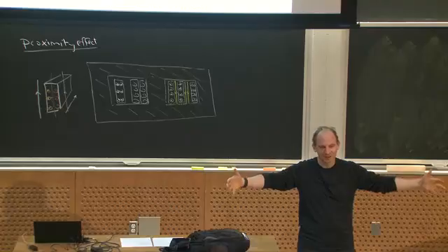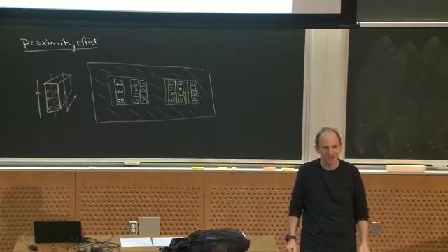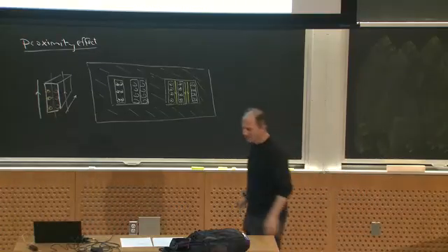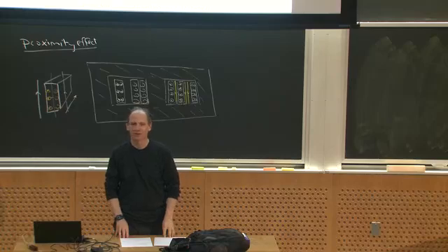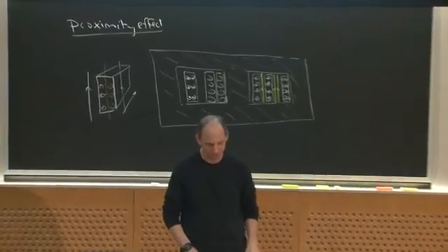If I'm building a 60 hertz transformer that's carrying an amp, my conductors are naturally going to be much less than the skin depth, and I wouldn't even think about it. Okay, so that's winding loss, right? And these are just some things to think about. Watch out for skin effect and really watch out for proximity effect if you're carrying high AC currents.